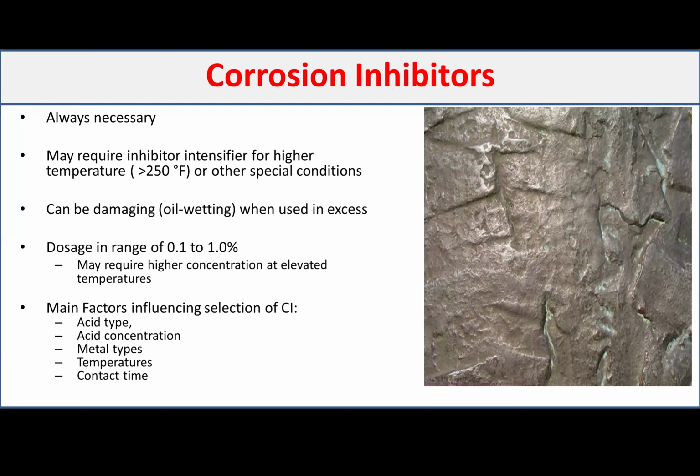Also, temperature and contact time will have an effect, but usually the temperature and contact time affect more the concentration. So the higher the temperature, the higher the contact time, usually you need to use more and more of the corrosion inhibitor. The concentration will go up.